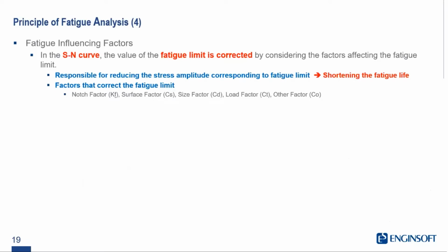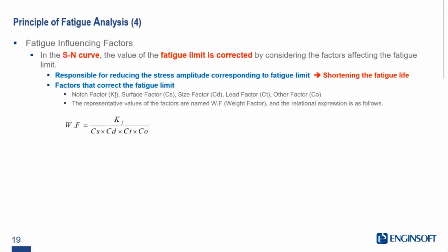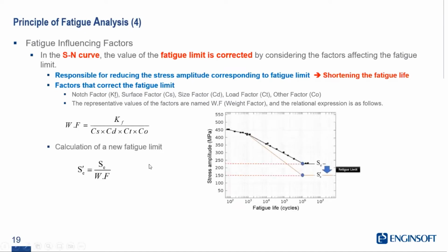So next, we're going to continue down the idea that what we've talked about so far is an idealized world. When a materials lab is doing the testing, they're assuming that you have perfect samples, right? In reality, that's never the case. So we can apply corrective factors to our SN curve to account for things like stress concentration zones or the effect of, well, I'll go through these pretty quickly, but basically you can apply some factor to the SN curve to get a modified or corrected SN curve. Then you use that for evaluating your lifetimes instead.